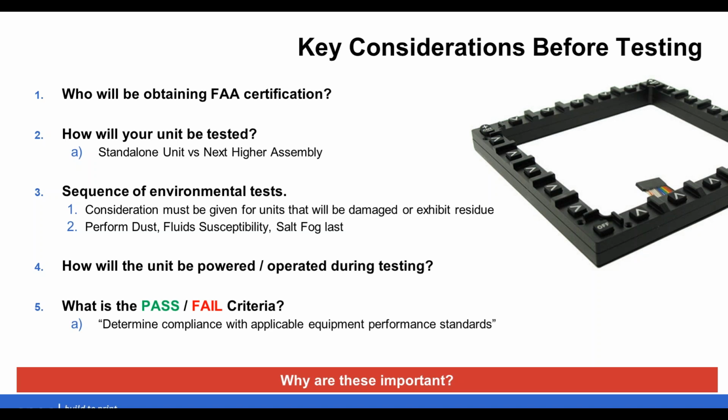The key here is that some of the tests like sand and dust, salt fog, fluids susceptibility, all of these can damage the unit, create some kind of residual buildup, and negatively impact the test later down the line. So it's really important to understand how many units you're going to set into motion for your test project.